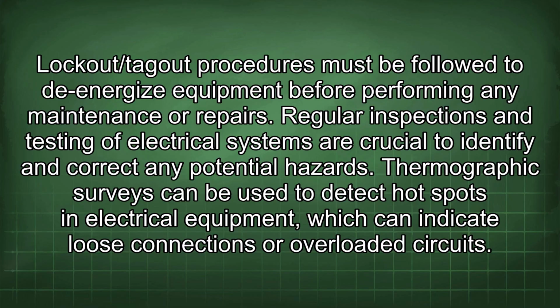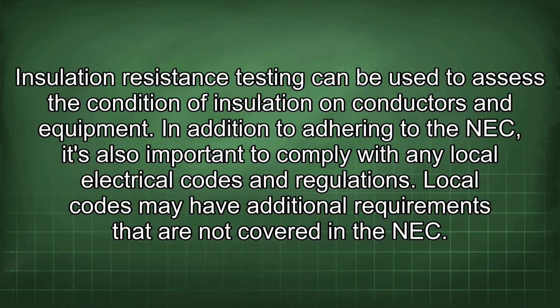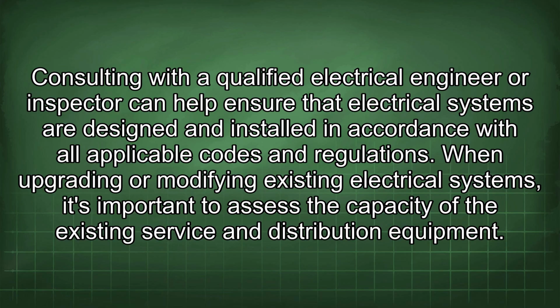Thermographic surveys can be used to detect hotspots in electrical equipment, which can indicate loose connections or overloaded circuits. Insulation resistance testing can be used to assess the condition of insulation on conductors and equipment. In addition to adhering to the NEC, it's also important to comply with any local electrical codes and regulations. Local codes may have additional requirements that are not covered in the NEC. Consulting with a qualified electrical engineer or inspector can help ensure that electrical systems are designed and installed in accordance with all applicable codes and regulations.